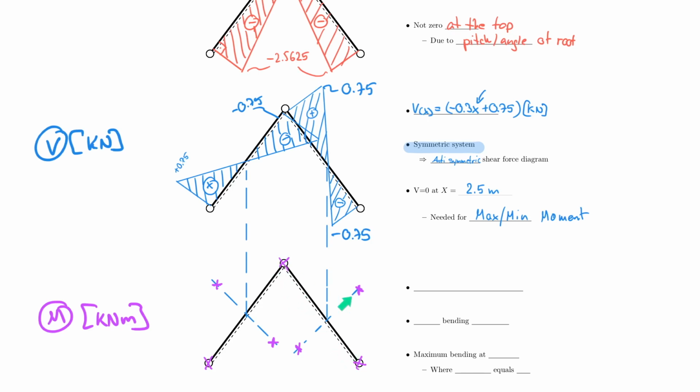Last thing now is positive or negative. So effectively, do I draw my arch this way or this way? And the answer is easy. If you remember, compression on the top, tension on the bottom is a positive moment. That is exactly what we have here, or as we called it in the class, the beam is smiling. So this beam here is literally smiling. It wants to bow down, and because it wants to bow down, the moment is positive.